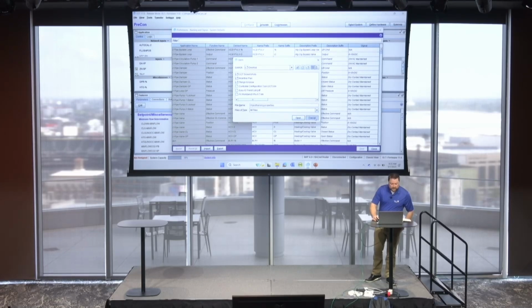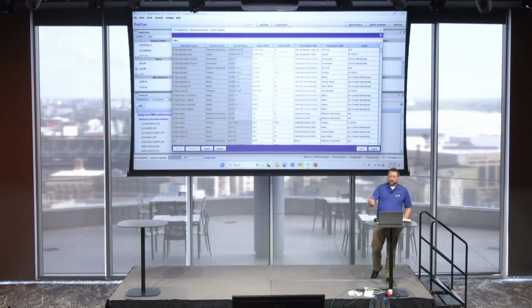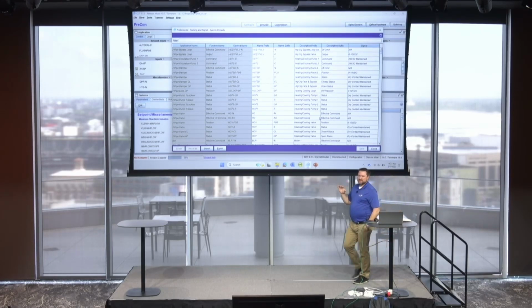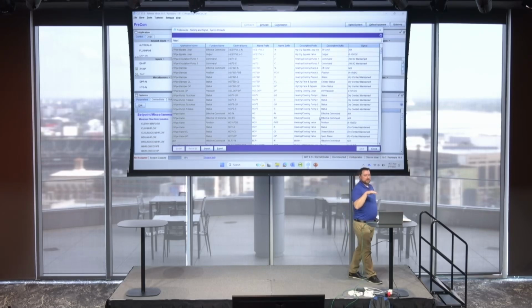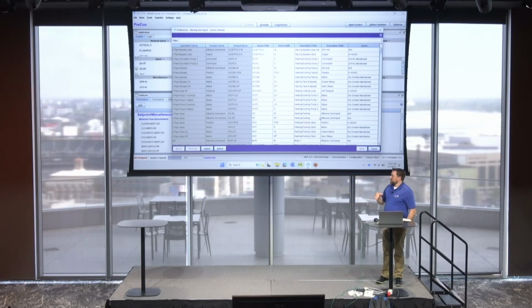Oh, I think I clicked. Oh, there we go, import. I might have spelled it wrong, but either way, when you go back to .properties, you can import it. It takes about 5-6 minutes to run that import, but now all your default point names will be underscores instead of dashes, right? So a couple different examples.